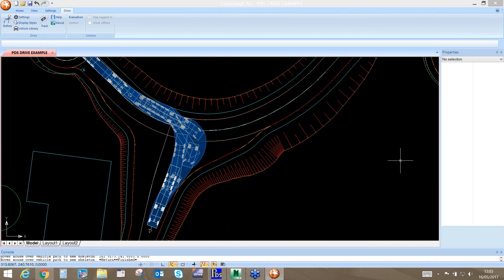As far as the .sws and .fws files that microdrainage produces, they don't actually hold the flow control information. They hold just the hydraulic information for the pipes and the nodes. So that's what we import at the minute. MDX is not a published format, is my understanding.